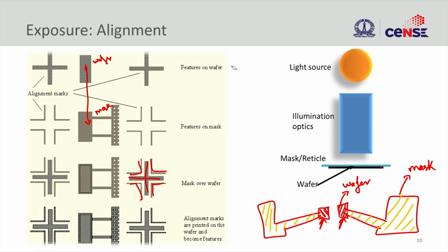In order to understand how to put these alignment markers, let us look at the alignment marker placement. If I take a circuit, and I have some circuitry, let us say something like this, I always put the alignment markers at the corner. If you want to be very careful about this, you can also put more alignment markers.